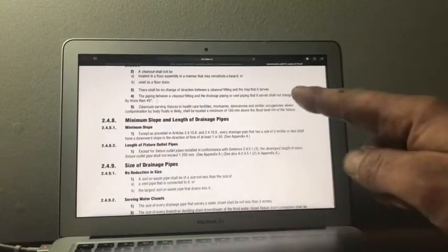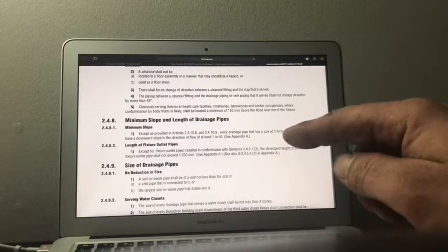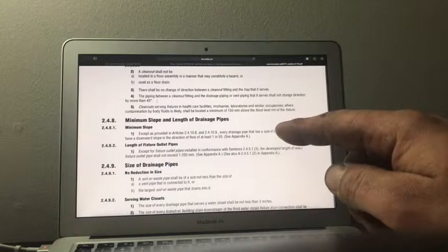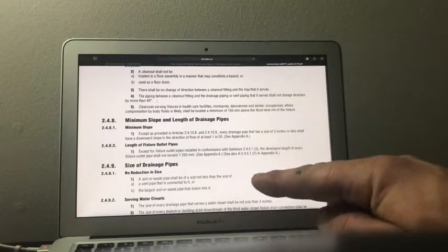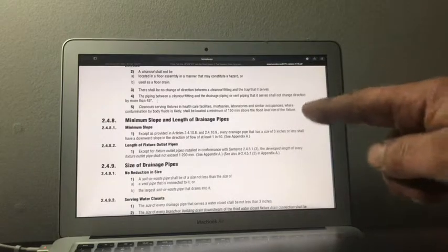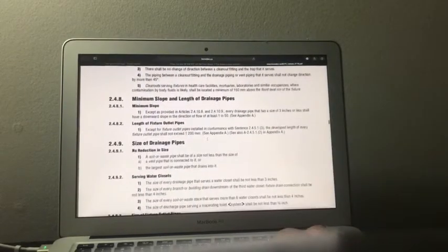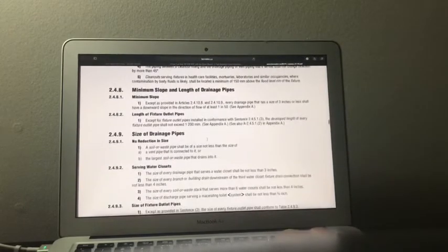So traditionally, the inspector lets us put a clean out right here above the floor, let's say in mom and pop's bathroom sink or kitchen sink, and then we can generally do 3 turns below the floor before we have to put a clean out in. And that's kind of the same for drainage in a parkade: 3 to 4 turns, but 5 turns, that's unacceptable. 4, you're pushing it.